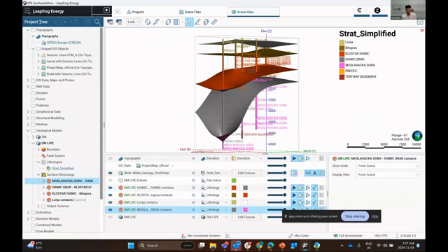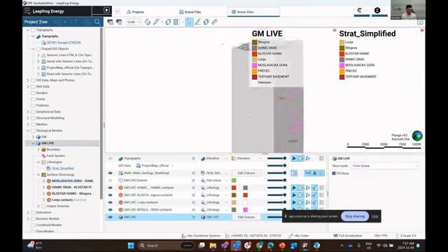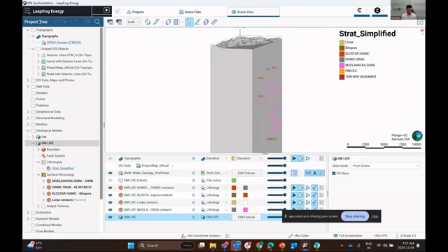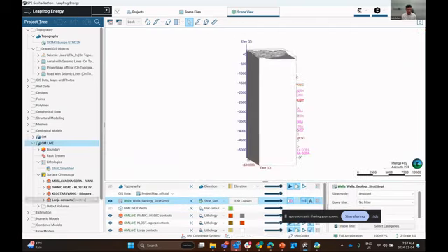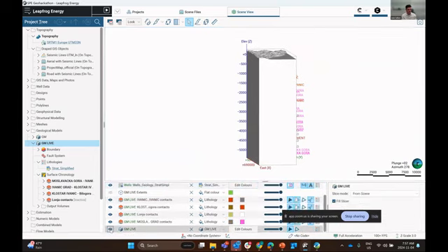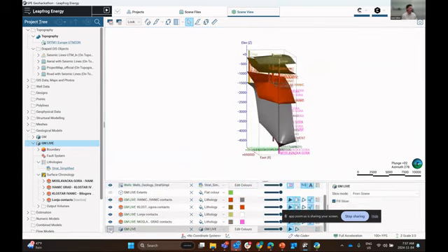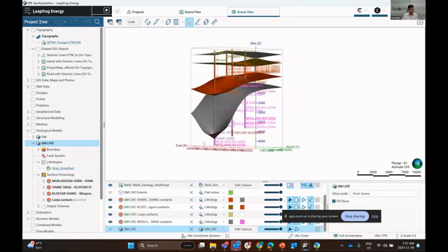So although we have these surfaces that are representing the different geologic contacts, you'll notice if you drag and drop your geologic model into the scene, that it is still this unknown volume of rock, even though we've defined the contacts associated with each unit. So the way that Leapfrog works is these surfaces that represent geologic contacts have to be activated in order to generate volumes associated with each rock type.